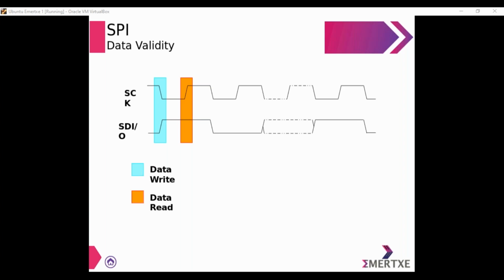So here is an example which shows edge detection. The communication is happening with respect to the edge of a particular clock pulse. Whenever the clock pulse has a falling edge, whoever wants to transmit the data will be transmitting. That is why you can see a change of data from 0 to 1 or 1 to 0.